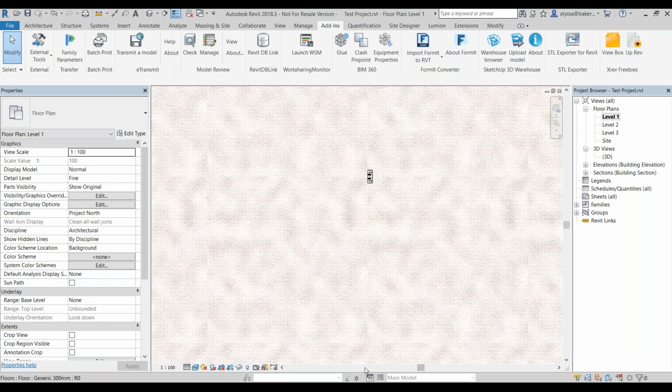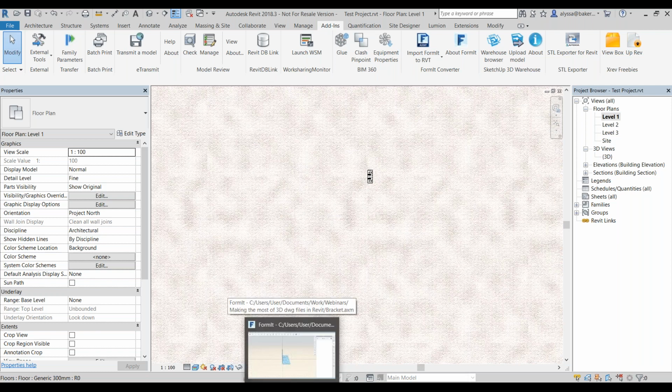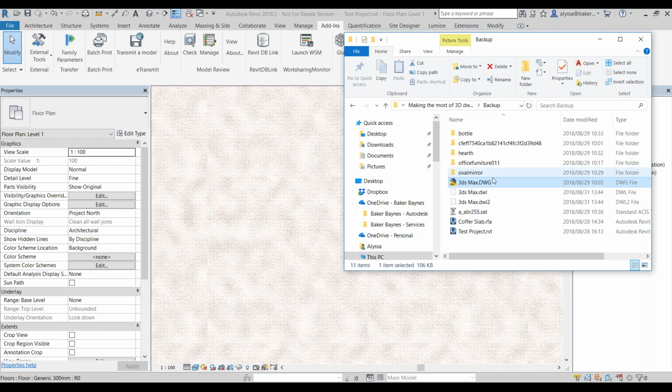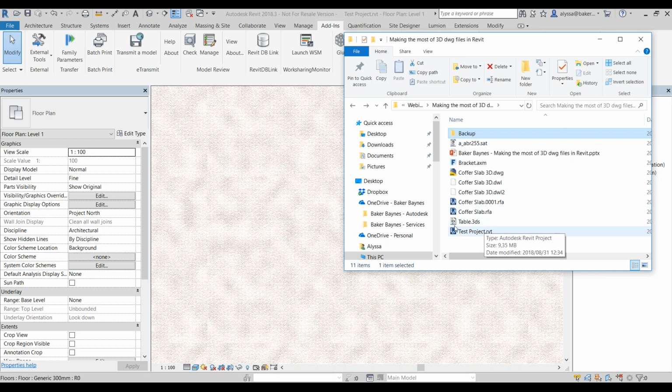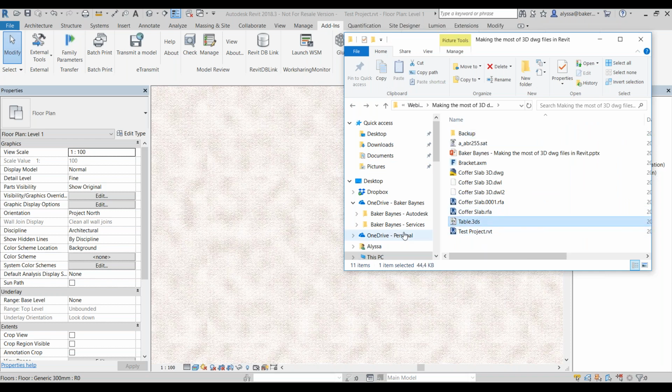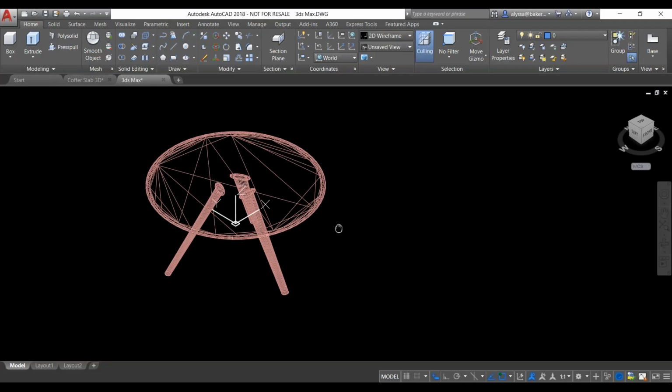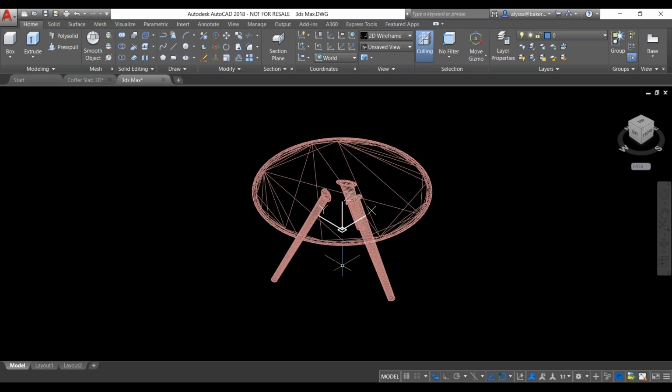All right. The last method or solution that we came up with was using 3ds Max to bring in a few other objects. Unfortunately, my application is not working, but I was smart enough to save a backup file. Essentially what I have done is I've taken my table, which was in a 3ds file format, into 3ds Max on a blank scene, and then exported it out as a table DWG. It's just a normal DWG. I've just named it table.